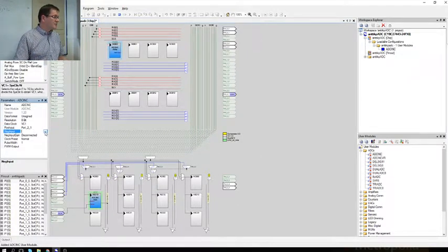The negative input: now we are using a unipolar signal, so basically we just neglect that one if we have the disconnected negative input gain. It means that we are using just a single-ended signal. In the exercise, you will be using this signal from a variable resistor, which is on the same board, and therefore you don't really gain anything by having differential signals.